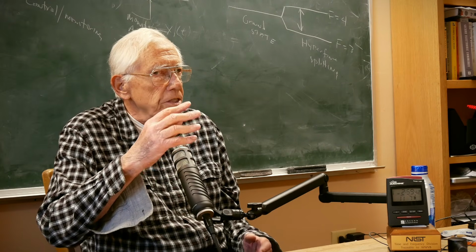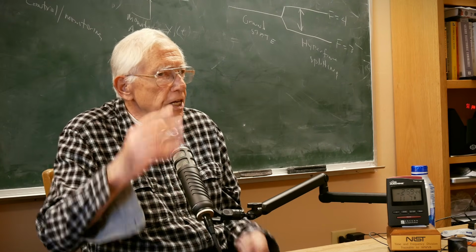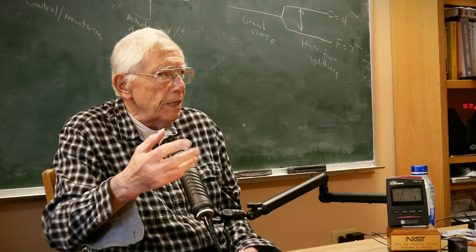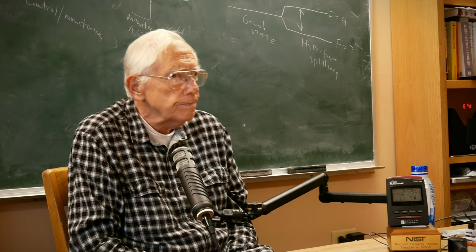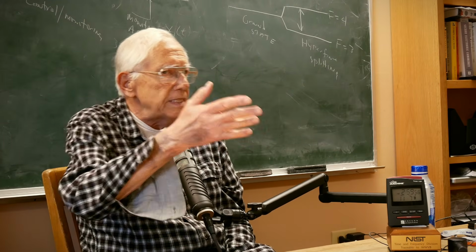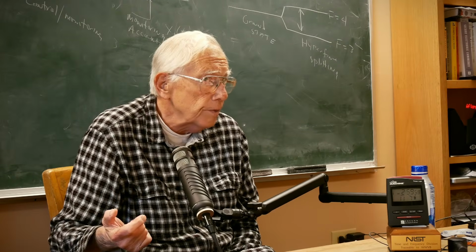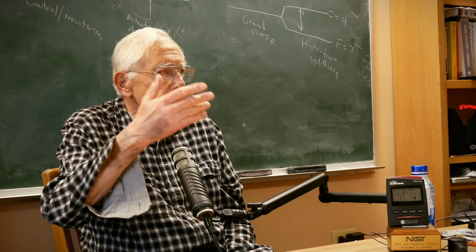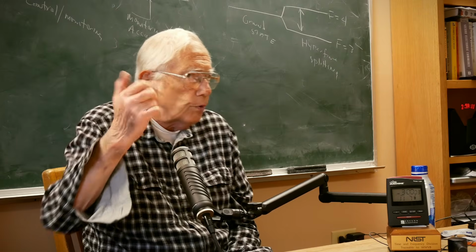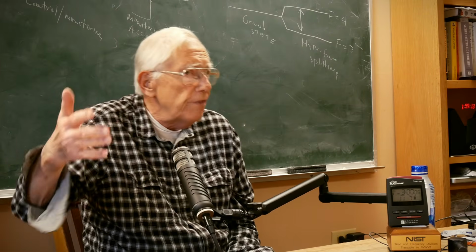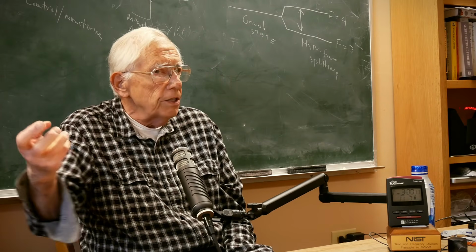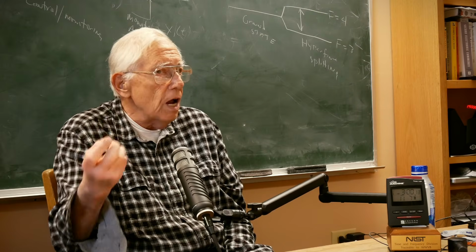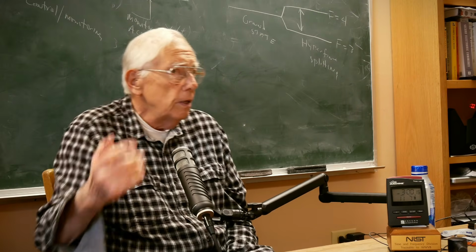But you have to distinguish between engineering and fundamentals. The amplifier is engineering. Sure. But the divide by 2 is fundamental. That's fundamentally what's going on. And now the only difference is that in the cesium standard, the frequency is much higher. In the cesium standard, the frequency is 9 gigahertz. It's in the microwave region, so I have to do many more divisions. But it's the same idea. I divide until I wind up with a frequency that I can use to drive a display, a counter.